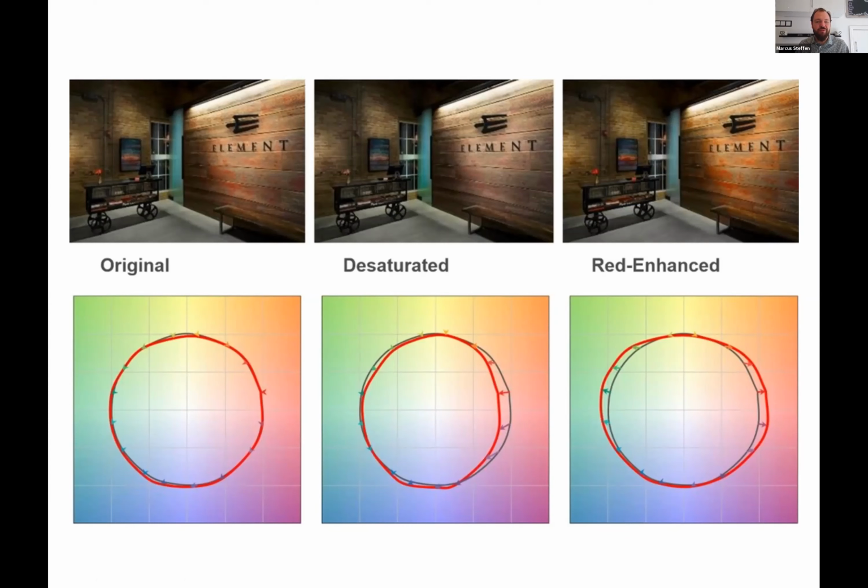It doesn't have the flaws of CRI, where people are using an average of the first 8 values rather than all 15. A lot of people are moving towards using this as a way of measuring, and it is more helpful. It might become more of a standard in the future. At the moment, quite a few manufacturers are publishing details and having tests done to this. Color rendering is important, but both are important: color temperature and color rendering.